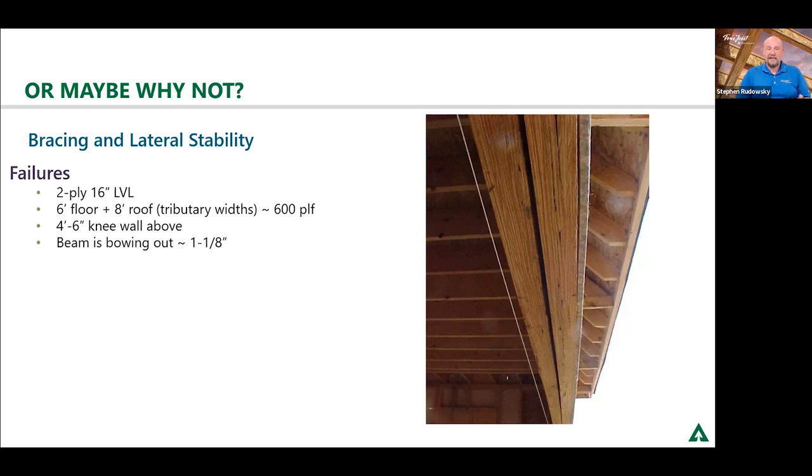So how you could brace that is bring that all the way up and put the header on top where the floor joists are and cripple down. So put that 4 to 6 foot instead of a knee wall, cripple down into your garage door header. How you just brace that entire length would be with the floor joist. And in some instances, you can actually brace that length.